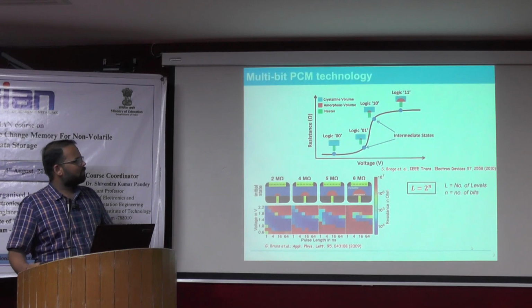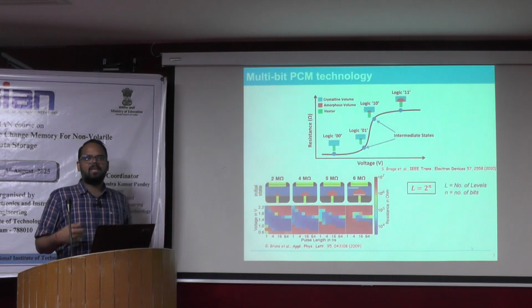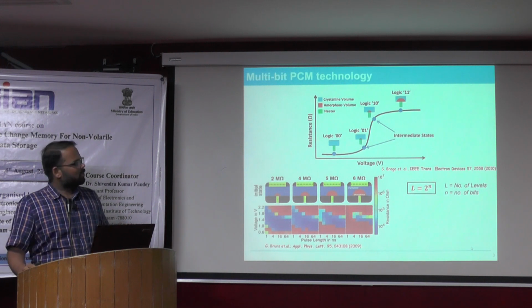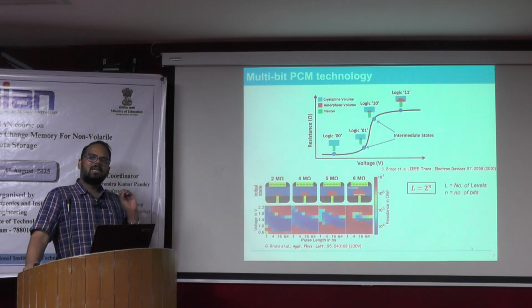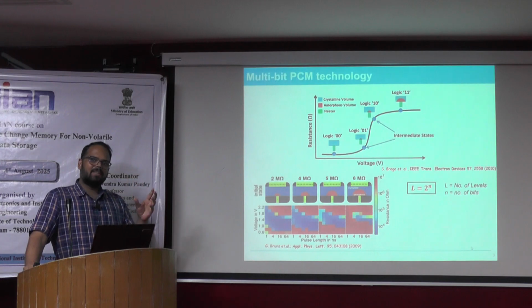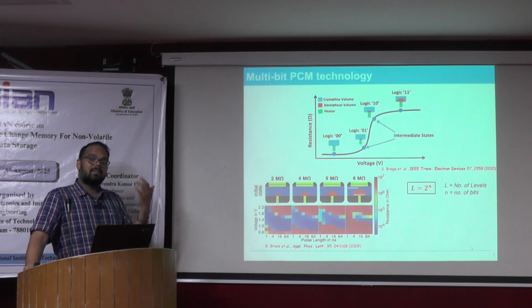So the overall thing is that identifying the resistance of the material is also very important. Although this is the programming curve, initially how the material is performing, what the resistance contrast is, that is very, very important. For that, you need a resistivity measurement to identify the thin film. This is the prior and most important thing, to understand how the material contrasts. After identifying a material, first you have to identify its resistance contrast, and with the help of that